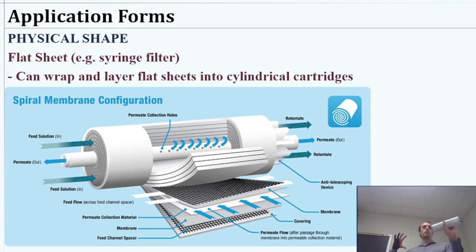So we have water applied essentially on the outside of this, so it can go through to the other side. It can meet the membrane, a lot of surface area here, and it can go through, and once it passes through, it's in the other channel. It's kind of like traffic, you just have to guide the traffic in the right places. You don't let the cars go in a certain way. There's just a physical barrier there, right? So if they pass through the membrane, then they can go along their way and ultimately find their way out. It's a little tricky or a little clever, I would say, but we can get a lot more surface area into what we would call this cartridge or spiral wound membrane.